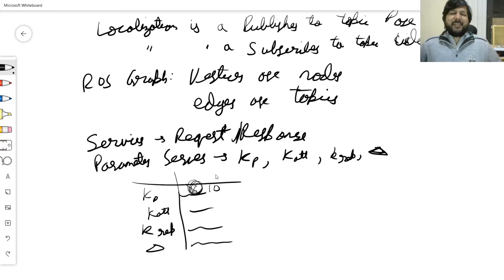It actually becomes very important because, you know, from research, a lot of effort is spent towards parameter optimization. And remember that for every parameter change, you need to recompile your program, reinstall the software suite, which is your program only, and then rerun it. It takes a long time. What if I could do it on the fly by giving commands to the parameter server and just rerun it? So that's something amazing that ROS does provide.